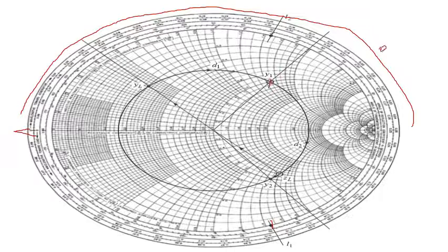So from here, the entire way up till here, it is always 0.25 lambda. I hope you know that. I have told you before also. The entire circumference is always 0.5 lambda. The half will be 0.25 lambda. So this 0.25 lambda and the point up till here is coming out to be 0.347 lambda. If you ask me how much distance has it traveled, we always subtract this 0.347 lambda minus 0.25 lambda, and the net value you get is 0.097 lambda. So the value of L1, when it is short circuit termination, has to be 0.097 lambda.